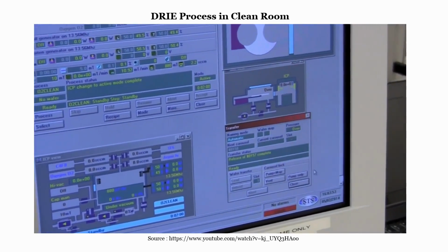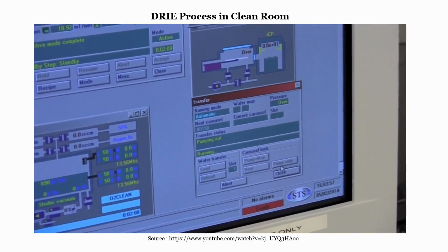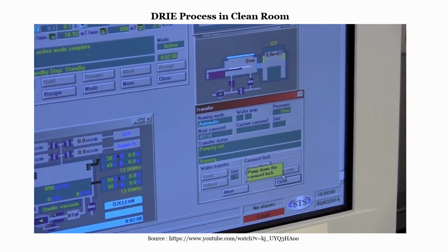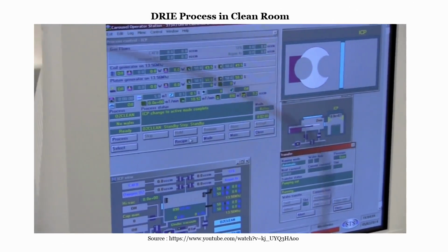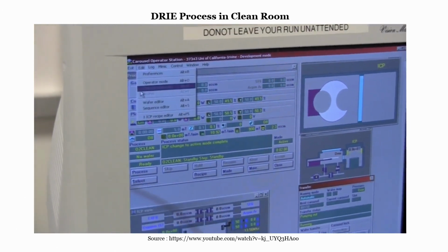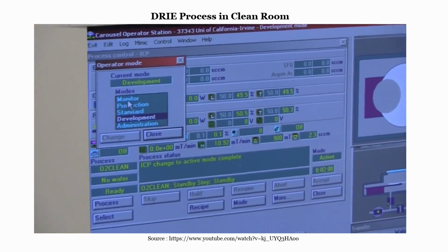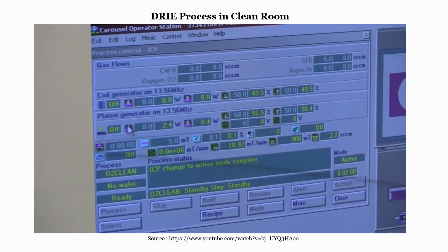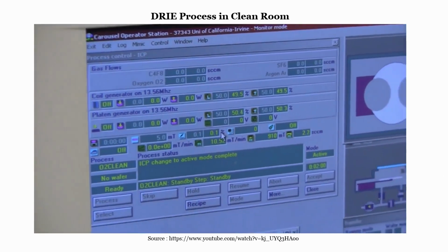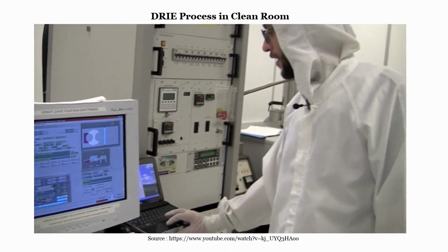We do that by clicking pump only in the transfer window, because we won't be processing anything else, and nobody is after us. We will go to the edit menu, go again to operator mode, and press monitor to put it into standby. Once we've done that, the next thing to do is to log off from the laptop.